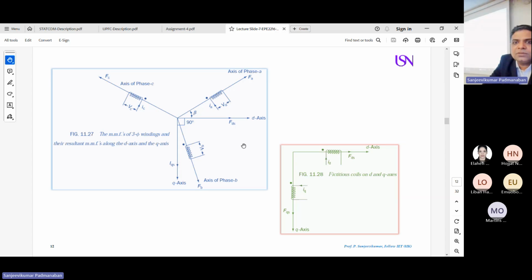For example, at a particular time, this is the way my active power and reactive power are phase shifted at an angle of 90. Now we rotate 360 degrees. It will rotate only at a fixed angle of 90. So you have already fixed your torque and flux, or I say you have already fixed your active power and reactive power. Now you rotate, you control this guy, its amplitude, you control active power. You control the amplitude of this guy, you control reactive power. So this is the advantage of going for these transformations.